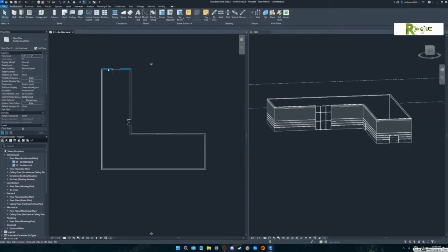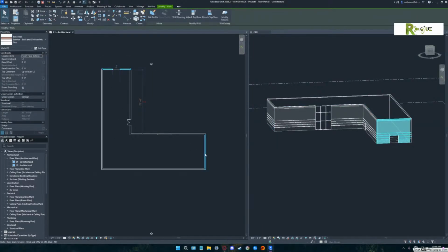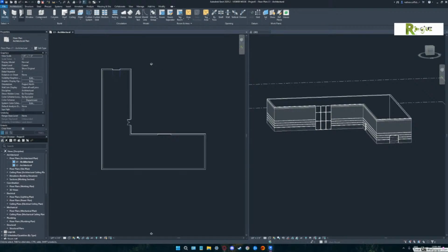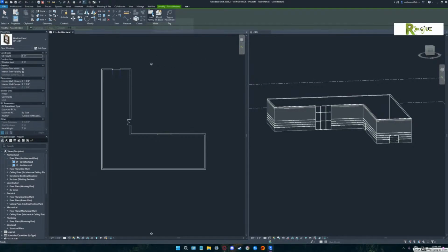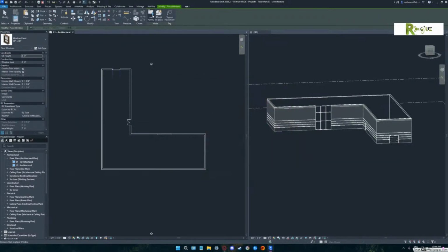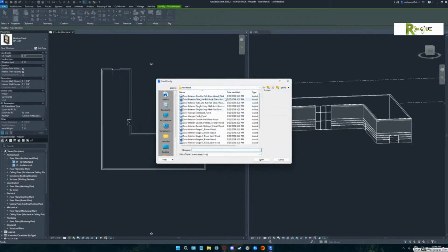We got you to load the families, and that was actually really an important step because that happens to about 60% of the people. So I'm glad that happened. Go place a couple windows. Do you want me to load the families, or do you want me to just do a window? Why don't you try to load a family or 2 if you want? You got to pick window first. Then that load family comes up. And you see you're in the residential doors.